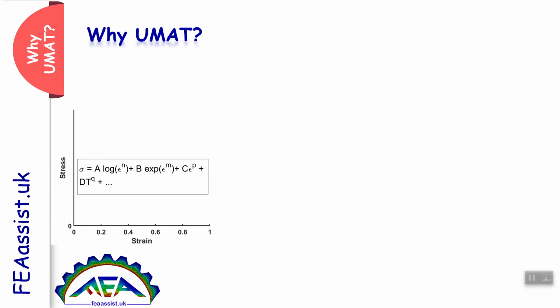The equation between stress and the components is very new, which is not included in Abaqus, and you don't have points. So what you can do? You need a place to write this equation or your equations and define Abaqus to obey this behavior to solve my problem.